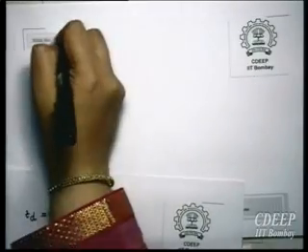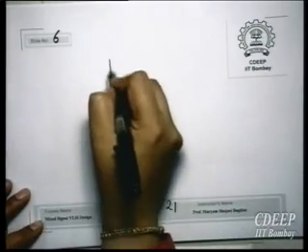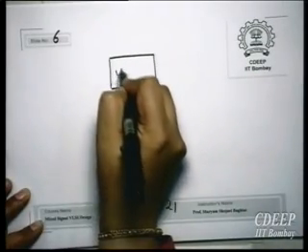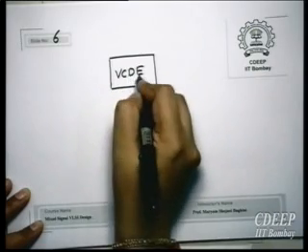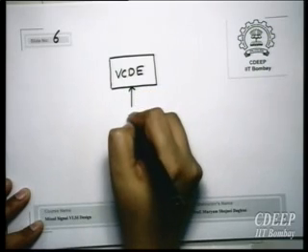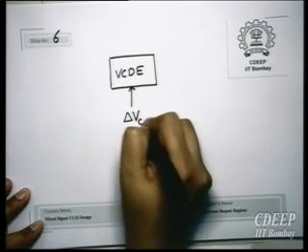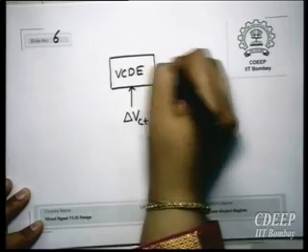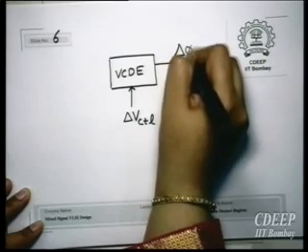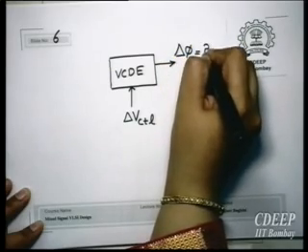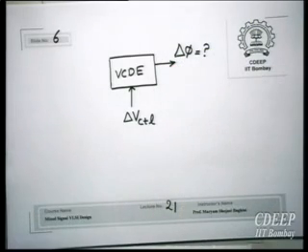See, why doesn't it have any impact? Because this is your delay element. In large signal, we are interested to see if I apply a change in input control voltage, how much phase at the output of this will change. What should be the corresponding delta phi? But this delta phi is not a function of that input. Therefore, it doesn't appear.